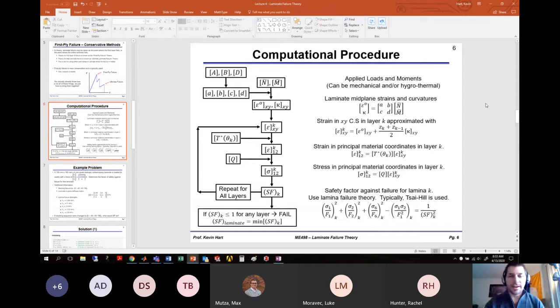You are going to create a laminate, and we're going to assume that you know enough properties of that laminate to give you the capital ABD matrix. Okay. So you know the stacking sequence, you know the constituents of the individual layers, and so on. You should have enough experience now calculating the ABD matrices that you understand how this happens. After calculating the laminate stiffness matrix from ABD, you can get the laminate compliance matrix by inverting that. Okay. So again, you've done a lot of this.